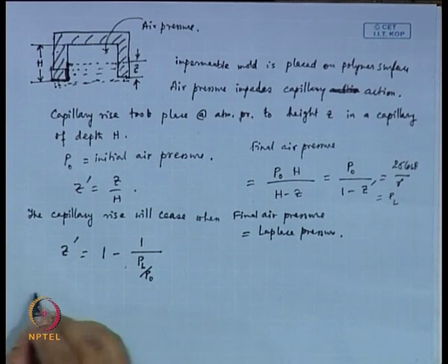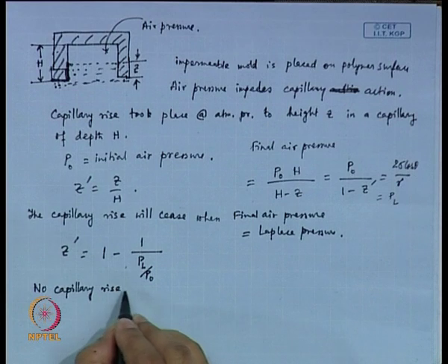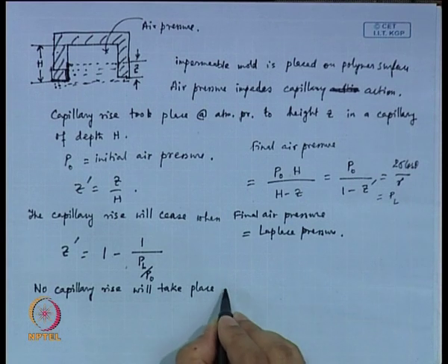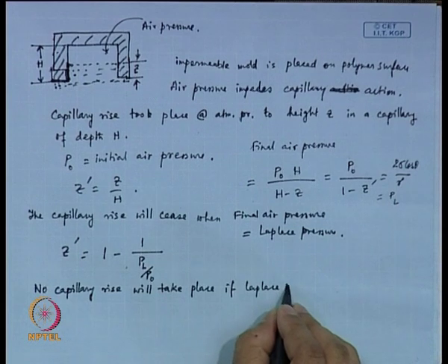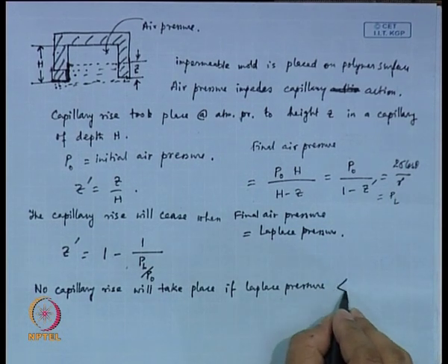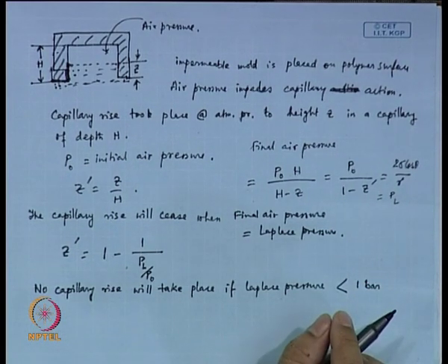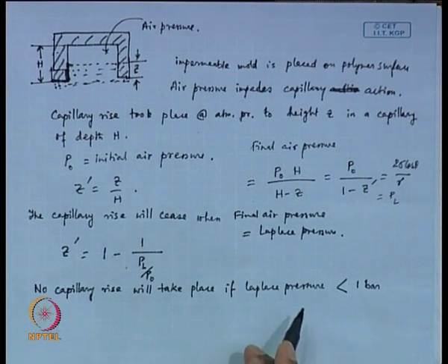Now, you need to understand a couple of things here. No capillary rise will take place if the Laplace pressure is less than 1 bar, less than atmospheric pressure. If it is less than atmospheric pressure, no capillary rise will take place. That is one issue here.